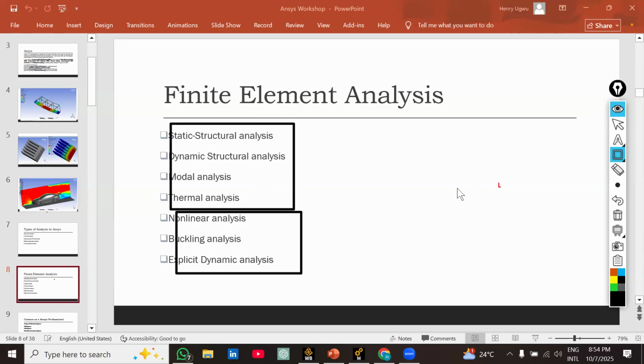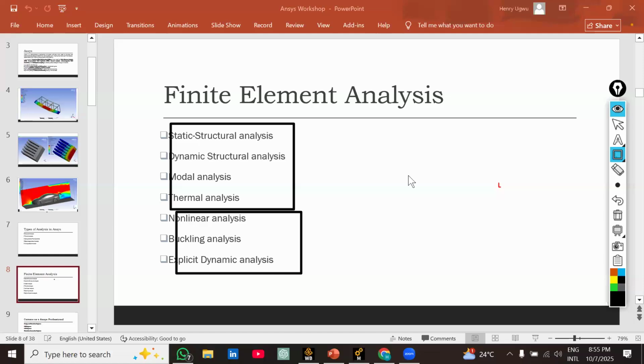Buckling analysis is to determine if a structure will buckle under a constant loading condition, under any loading condition. For instance, your telecom mast. You know that it's a very slim, tall structure. You have loading conditions from the wind and from the weight of the things attached to the mast. If rain is falling and there is a large wind, weather changes do affect the structural integrity of that mast. So you can do an analysis to determine if those load conditions will make it buckle.